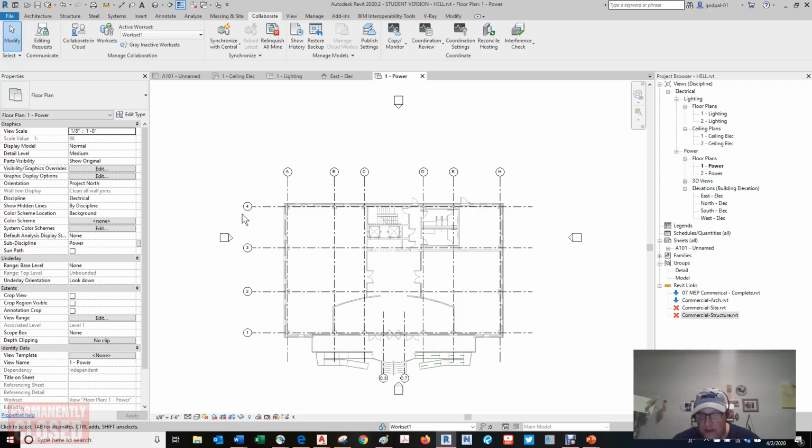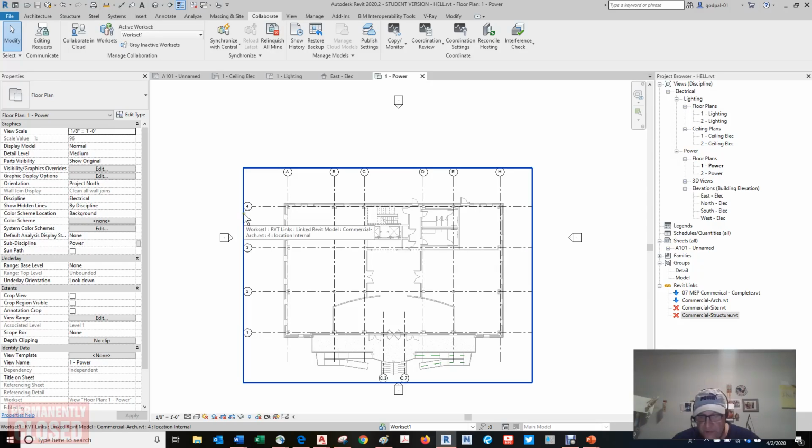Use this tool to highlight any elements that are hidden in the current view, either temporarily or through other methods. The work sharing display button is available only on projects where work sharing is enabled. Work sharing display can be enabled and configured in any view to illustrate owner's checkout status, model updates, and worksets. Refer to Chapter 5 for detailed explanation of these visibility features. The Show Hide Analytical Model button allows you to quickly display analytical graphics that are commonly used by the structural and MEP tools in Revit. Finally, the Reveal Constraints button temporarily displays all the model-based constraints visible in the current view. This is useful for troubleshooting model elements that might not be behaving as expected.